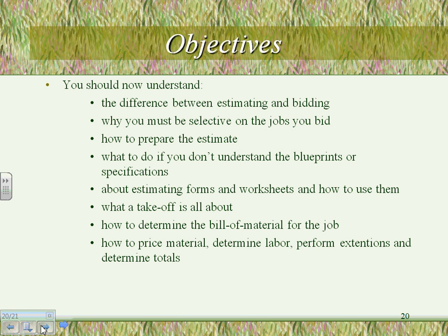Figure 4-1. Can you guys see the fixtures? This is how you're going to be taking off the project for me. They have lay-in fluorescent fixtures, 18. That's a takeoff, counting them. And exit fixtures, 2. Switches: single pole, single gang, 1. Switch 3-way, single gang, 1, and so forth. Receptacles: convenience receptacles, 9. IG receptacles, 2.